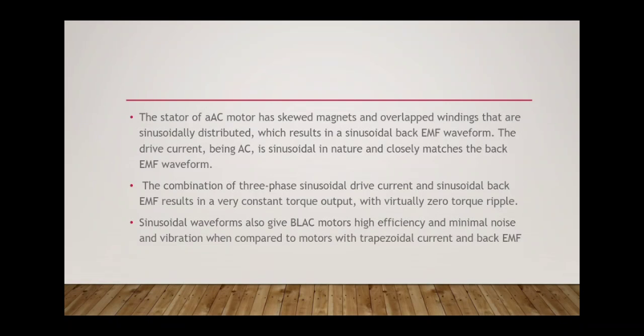The combination of the three-phase sinusoidal drive current and sinusoidal back EMF results in a very constant torque output with virtually zero torque ripple. Sinusoidal waveforms also give real AC motors high efficiency and minimum noise and vibration when compared to motors with trapezoidal current and back EMF.